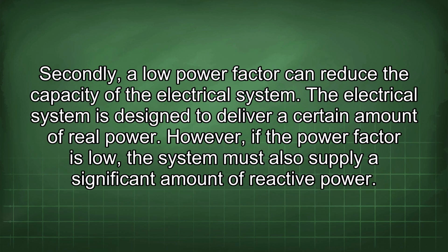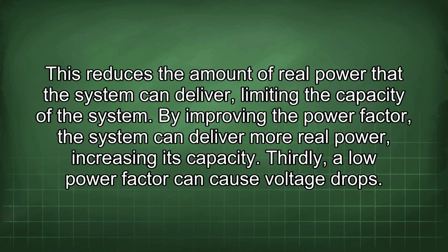Secondly, a low power factor can reduce the capacity of the electrical system. The electrical system is designed to deliver a certain amount of real power. However, if the power factor is low, the system must also supply a significant amount of reactive power. This reduces the amount of real power that the system can deliver, limiting the capacity of the system. By improving the power factor, the system can deliver more real power, increasing its capacity.